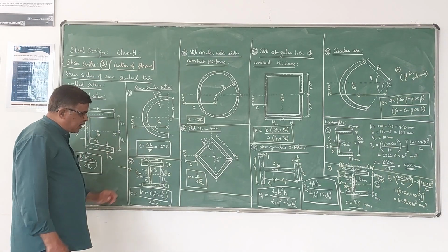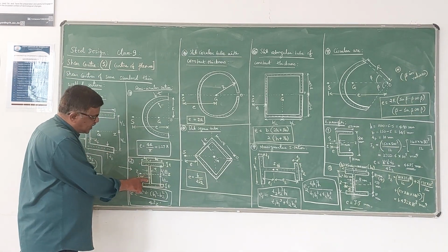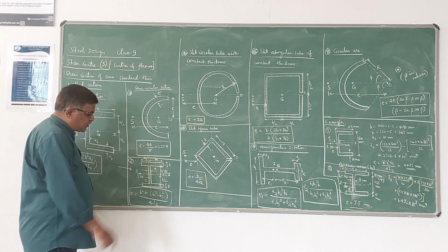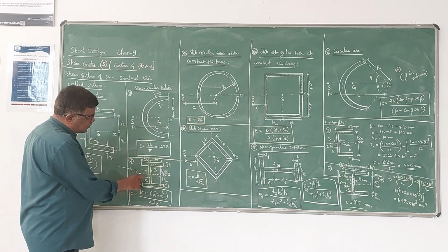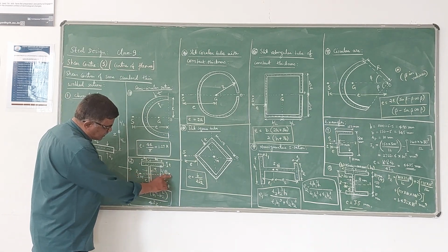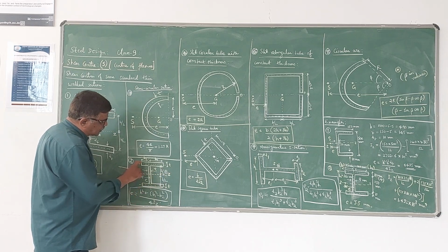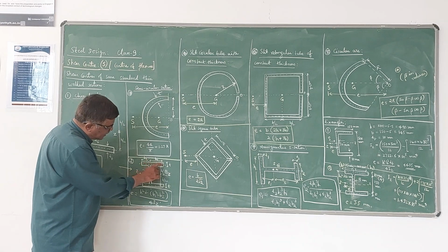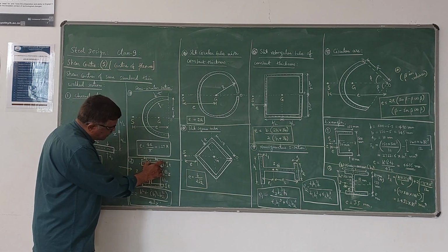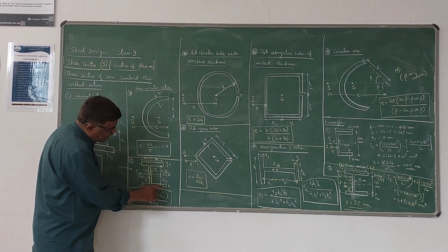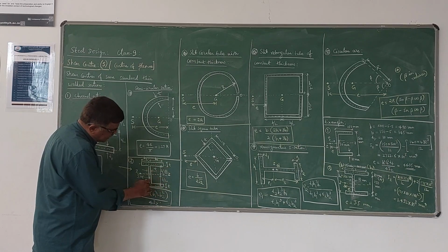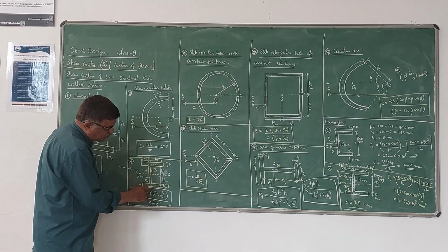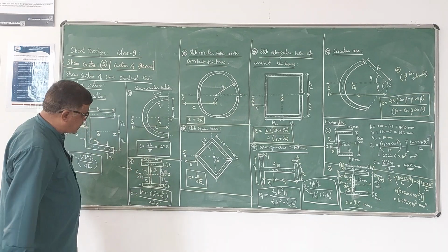Another is an I section, which is once again symmetrical about one of the axes. It is symmetrical about the ZZ axis. You can see here B1, B2, they are the widths to the center line, that is the width across the center lines. And T is the thickness. Let us say T is the thickness. It has uniform thickness for both flanges and web.